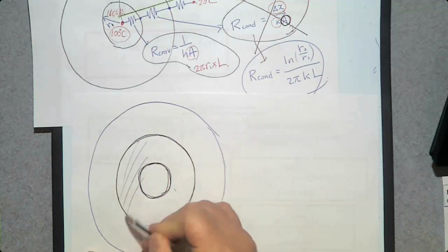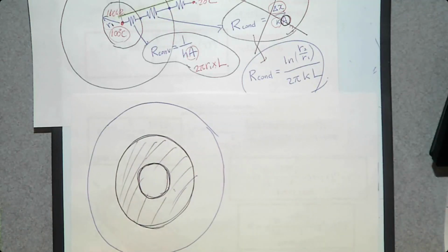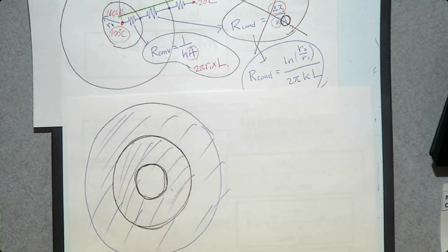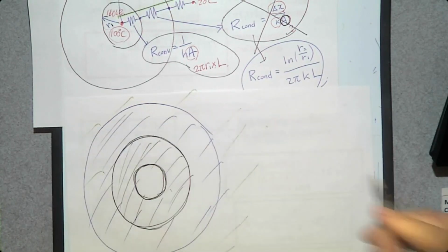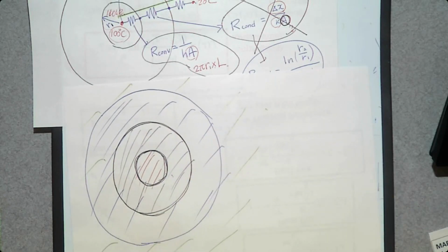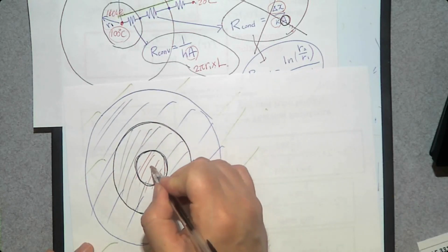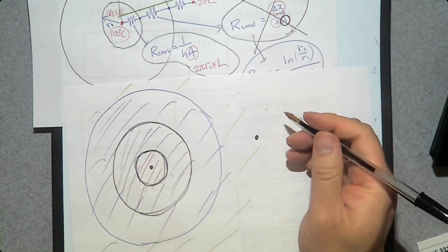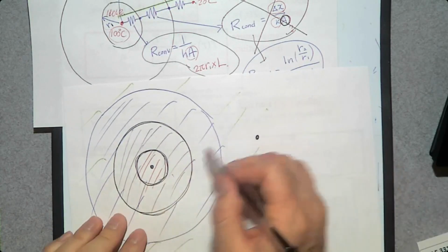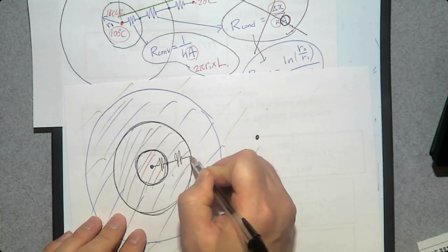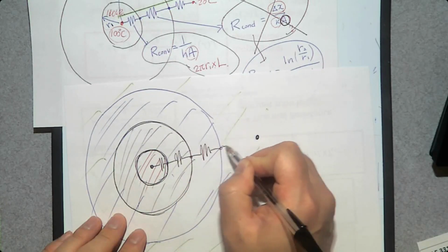for this pipe system, we are going to add an insulation, which is this blue. And there's air outside, which is going to be this green. Then what is the heat transfer from this hot water, which is this red? The direction of heat transfer is going to be from inside to the outside. And how many heat transfers? 1, 2, 3, 4. So conduction, convection, conduction, conduction, and convection.